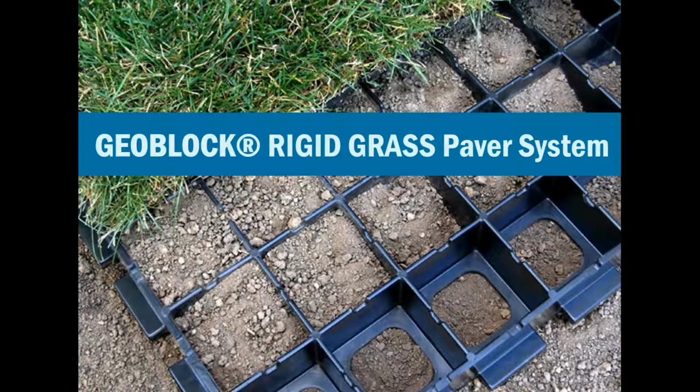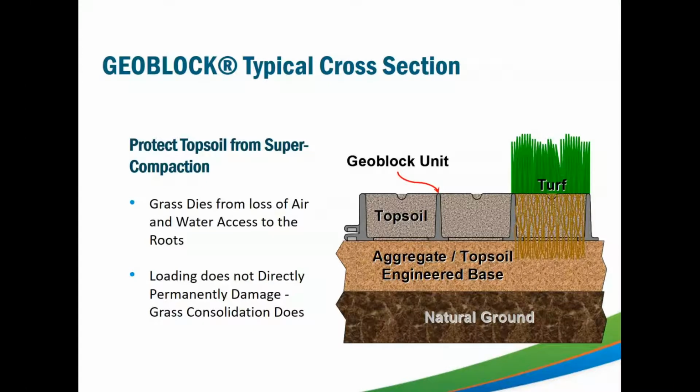So now we're going to switch and focus on the GeoBlock, the vegetated system. So here's a typical cross-section for the GeoBlock system. The GeoBlock panels come in 2 depths, either 1.2 or 2 inches. The depth of the overall system is also going to depend on the amount of base course that's required.